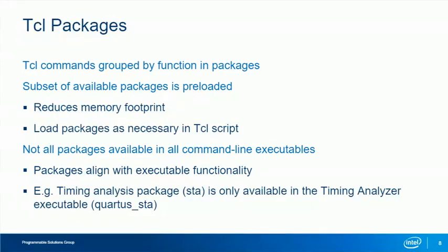Tcl commands are grouped by function in Intel Quartus Prime software Tcl packages. In each command line executable that includes a Tcl interpreter, a subset of the available Tcl packages are preloaded. This reduces the memory footprint, but does mean you need to remember to load additional packages as necessary in your Tcl script. It is important to know that not all packages are available in all command line executables. The packages available in each executable align with the executable's functionality. For example, the Timing Analysis Tcl package STA is only available in the Timing Analyzer STA command line executable, quartus_sta.